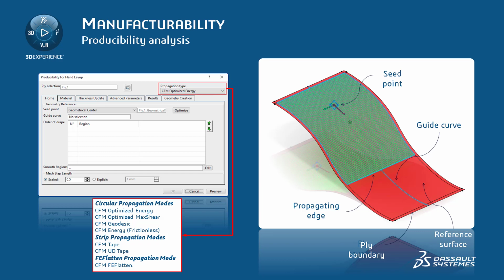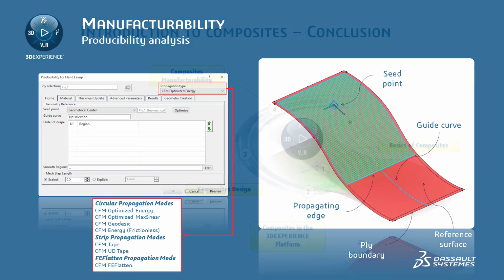After performing producibility analysis, you can perform a finite element simulation using Simulia 3DEXPERIENCE applications, like Mechanical Scenario Creation and Physics Results Explorer. In the case of a composite part, the following parameters are important to study: the stress, the Hashin failure criteria, the strain, the Tsai-Hill and Tsai-Wu stress-based failure criteria, and the thickness of the part.